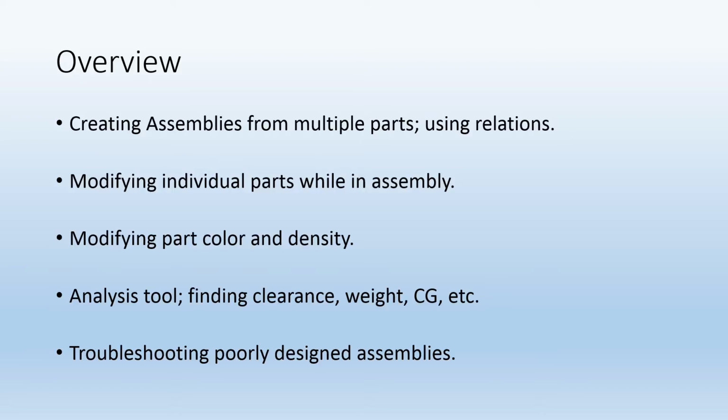And of course density, you can go ahead and set the density of your material so you can get an accurate estimate for, and it's the next thing we'll be doing, the center of gravity and also the weight. I'll also show you a really nifty clearance tool to understand how much clearance there is between parts, or if there's any overlap. So it'll help you understand if you've assembled something or modeled it correctly. And finally, my favorite is the troubleshooting poorly designed assemblies.